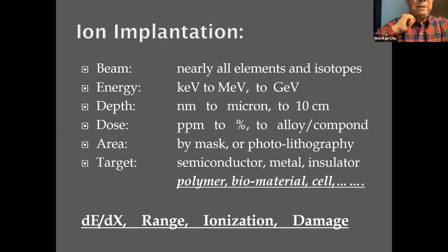If you only want to implant a single atom, then once the single atom passes through the hole and touches the substrate, he has to immediately shut off the beam by using a blanking shutter. On the other side, once the ion goes through, there's going to be an electron cloud around it. Once he sees the electron cloud, it automatically switches off the beam. Now he has accomplished a single atom implantation.